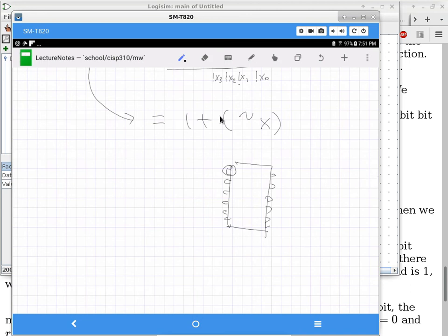It's an input pin, and I'm not going to connect it to something, because in CISP310, logic sim says if something is not connected, it's perfectly okay. So you carry that assumption to actual circuit board design, and you go, well, this chip is implementing a 4-input AND gate, of which I only need 2, so I'm going to leave 2 of those inputs unconnected. Logic sim says it's okay.